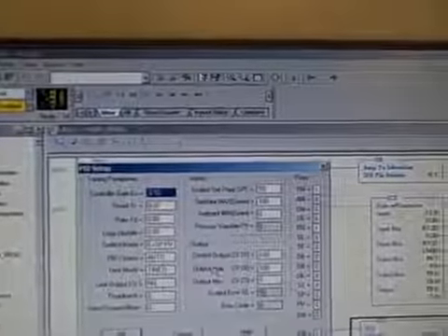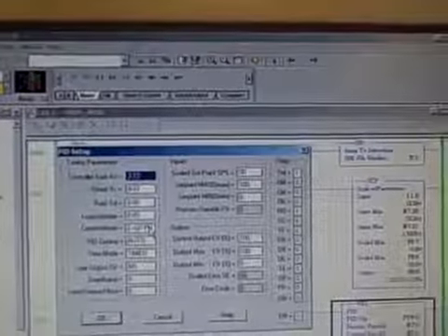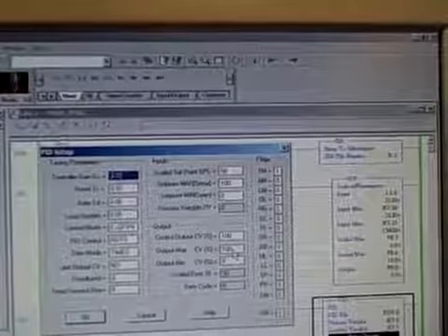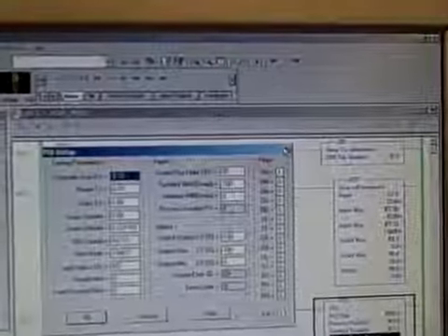But here, on our RS Logix Micro program, we're going to set up other things that operators normally wouldn't adjust, like control mode, or perhaps output limits or set point limits. And again, you simply enter the number, hit the Enter key, that's now saved in the PLC's RAM memory, and you are done. At that point, you simply come up here, X out of the program, save changes.